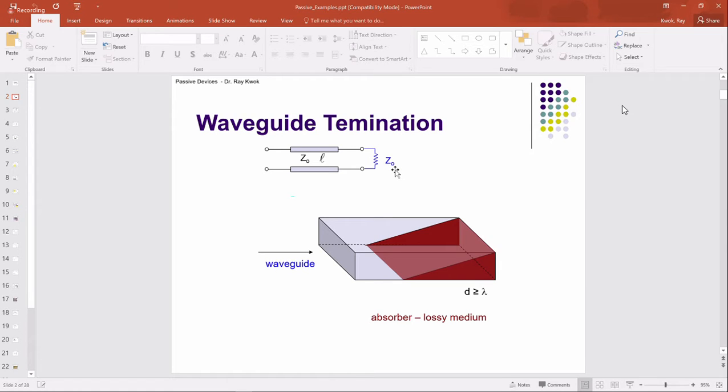So what's the point of that then? I mean, ultimately you want to get your signal from the waveguide. Why would you want to just block it off? Only if this is a two-port network, but for a multi-port network, as you will see later on, you want some ports to be loaded, to be terminated. Okay. Yeah, I'll show you a few examples later. But when we say terminator in waveguide, sometimes that's what it means.